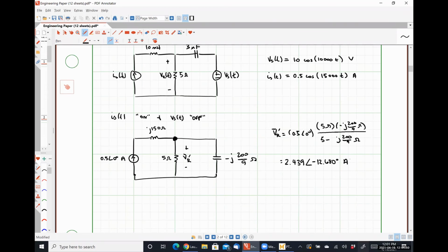One way to think about what we're seeing here is we have a passive amplifier. Anytime we have a resistor or an RLC circuit, we have the potential for having quantities come out larger than our input signals just due to the energy storage nature of things. So while you may see this and say, how did that happen? It's actually perfectly reasonable. Another thing we're not taking into account is the phase difference and things like that.